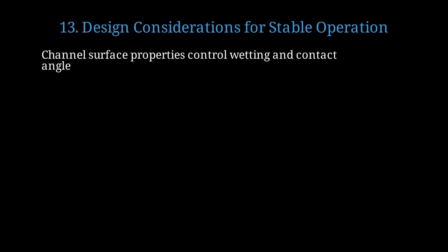Designing robust microfluidic systems requires careful consideration of multiple factors to ensure stable operation. The surface chemistry of channel walls controls wetting behavior and contact angle, which strongly influences flow patterns. The Young equation relates contact angle theta to the surface tensions at the solid-gas, solid-liquid, and liquid-gas interfaces.